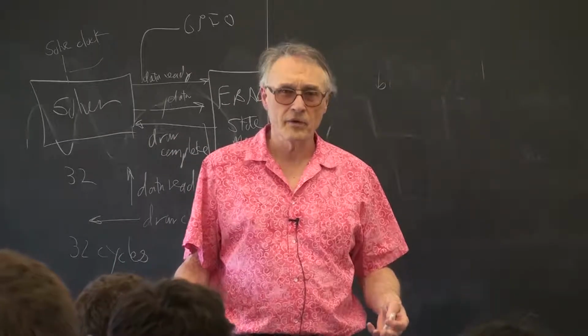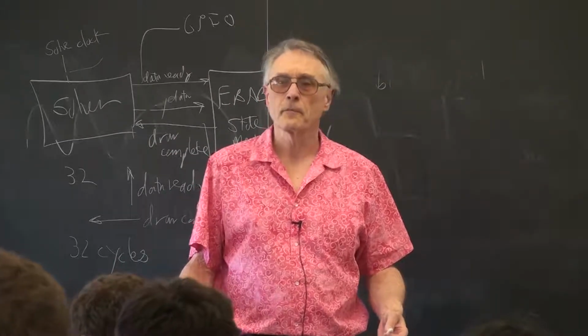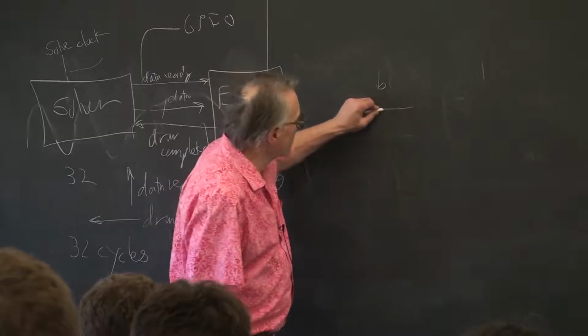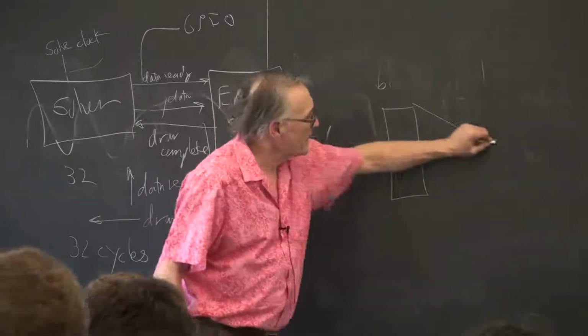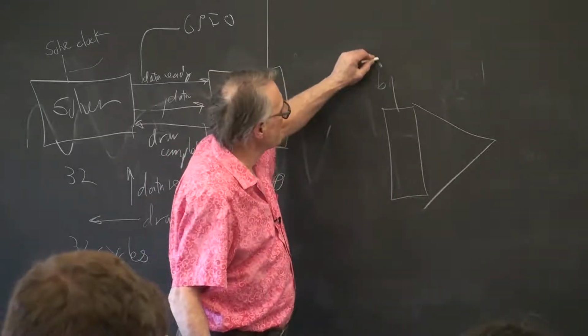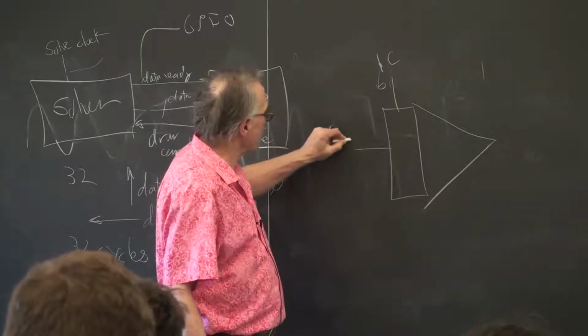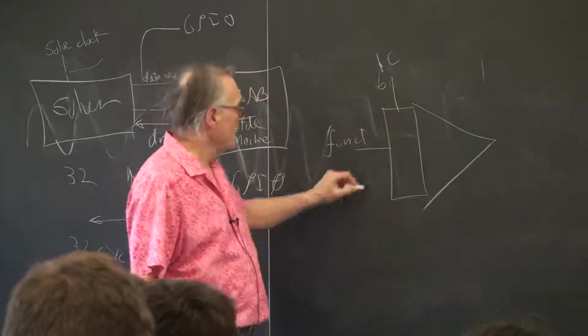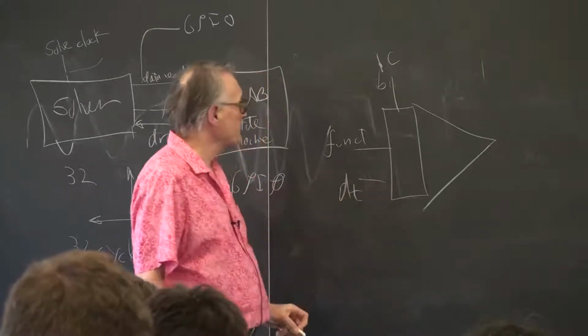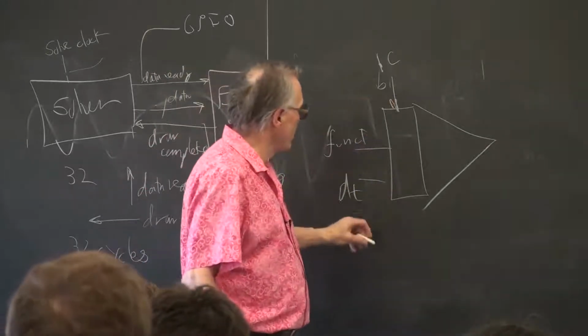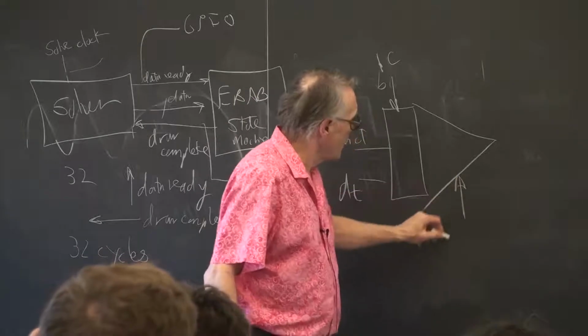It means to freeze the integrators. So if your integrator right now has an initial condition input, it has a function input, and a dt input, you could have another input which is hold.